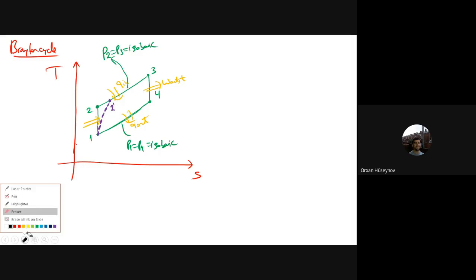Okay, and this is the working compressor. And from 2 prime to the next state here, it will not be isobaric. The pressure will drop. You will have something like this. Okay, and the pressure will drop to a value something like this, and here we'll have 3 prime. Okay, and then from 3 prime to 4, if it is isentropic, it will be in that manner, but in reality it will not be isentropic.